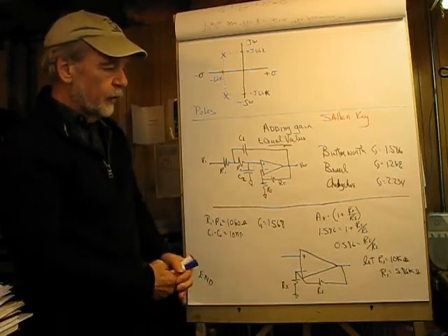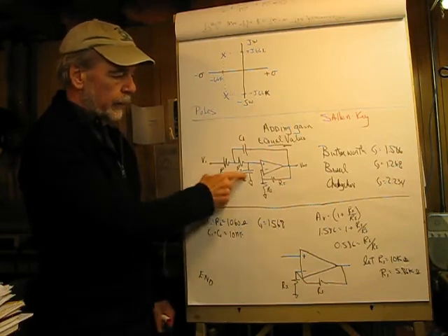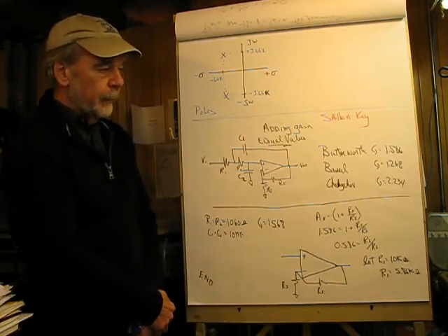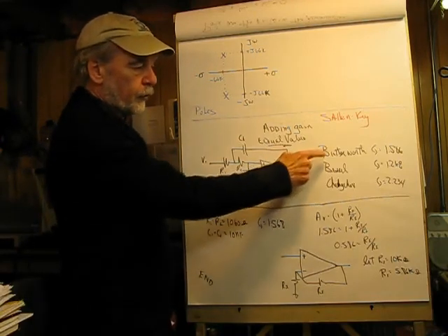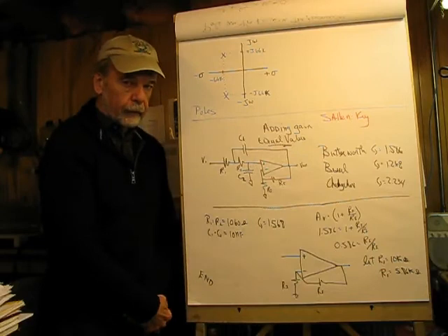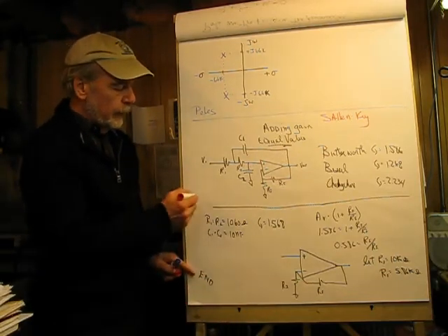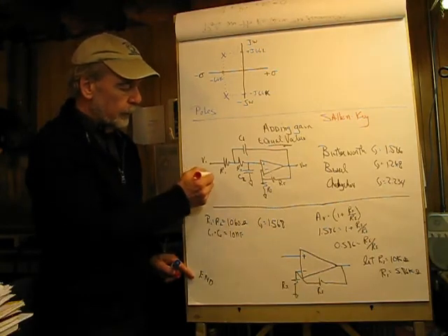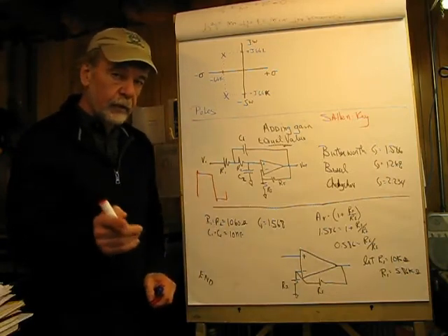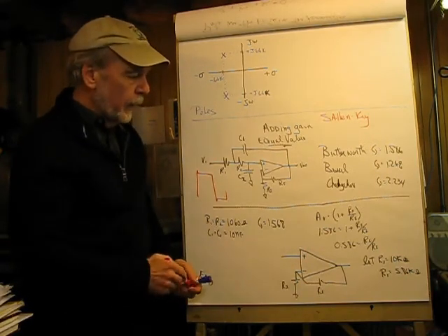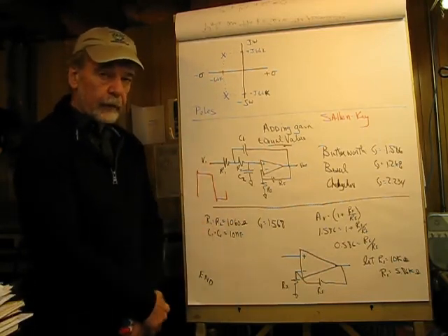So the second option is adding gain, and I've included two resistors here. These are all equal-valued parts again, and depending upon the gain I can get different responses. As mentioned before, Butterworth is maximally flat, and if you look at that handout, on transient response, hitting it with a square wave, it's got a little dimple at the top. That's the cost of getting something maximally flat. Now Bessel won't give you that; however, it's not maximally flat.